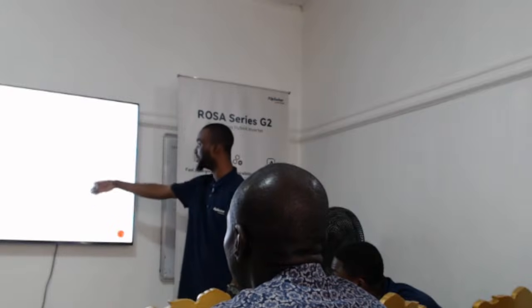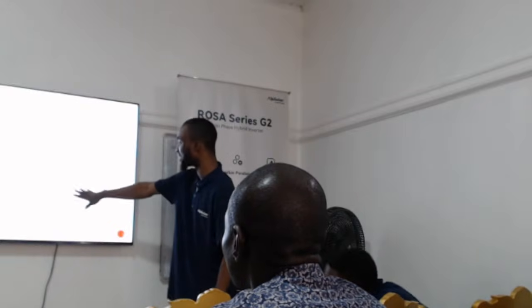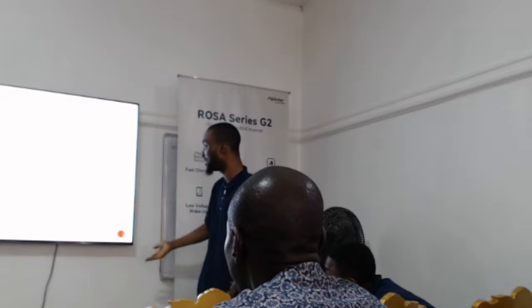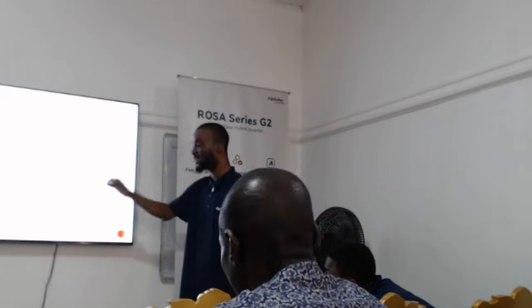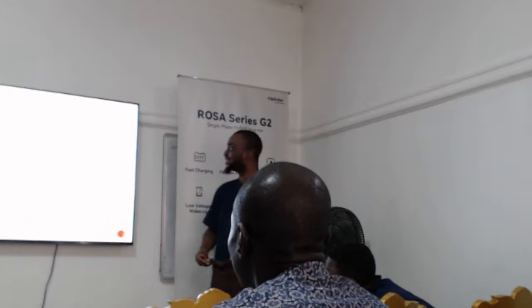So you can set your date, your year and your time with these settings. And of course, you can set your HMI, the human machine interface. How long do you want your inverter screen to display? You can set it like that. And if you want the warning fault light to be showing, you can put it. It is always on by default. Thank you, everyone. I think this should be the end of the settings.